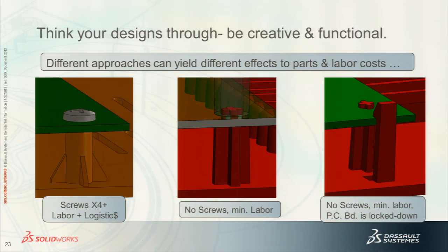Okay, but here I'm trying to show there are different ways of doing the same thing. You don't have to stay with the conventional mounting screws. You can use various types of molded in features to do the same function, and there are different types of cost and labor benefits by molding in these parts. Again, you'll have to pay a bit to get those put into your tool up front, but in the long run you will save labor and the hardware costs.